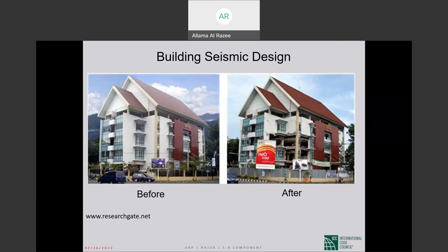Again, it depends on the region, because if you are designing for earthquake, in some locations there are not that many earthquakes, or if that happens, the intensity is small, so it's worth it that even for the earthquake we try to design them to remain linear elastic. But in many cases it is very costly.